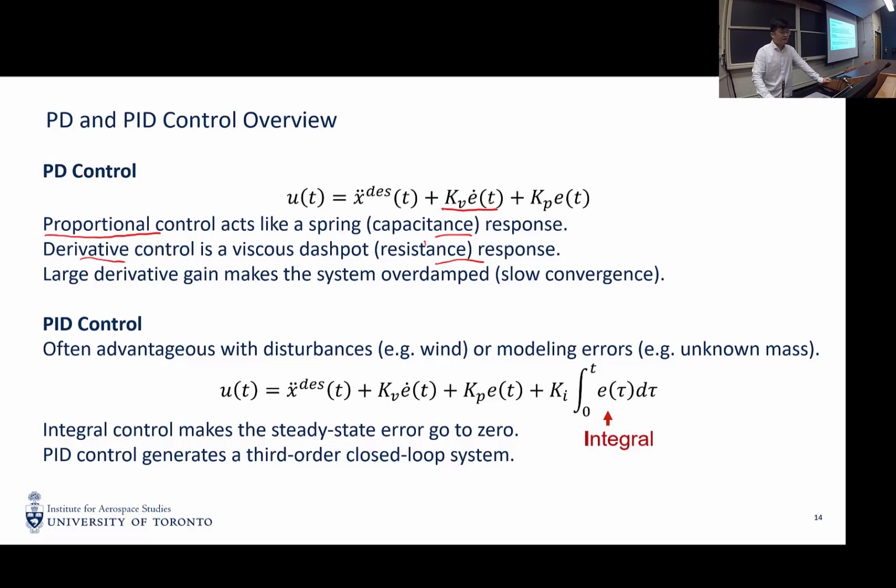More often, your system is not going to be solely driven by your control force. Quite often it will be affected by other disturbances. For example, for a quadrotor, we often need to deal with wind gusts, which contribute additional wind disturbance. In order to compensate for that, we need the so-called integral term. The idea is that if we do not have an integral term, we will eventually have a steady state error because of the external disturbance.